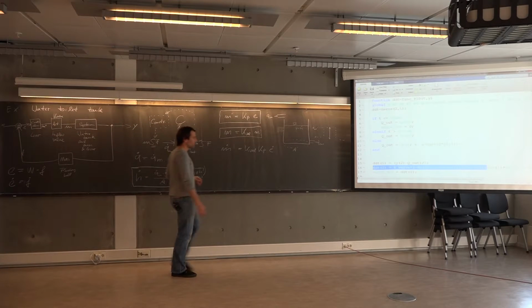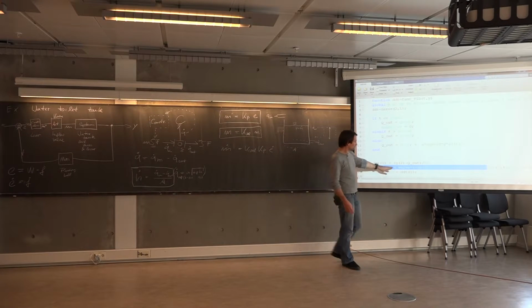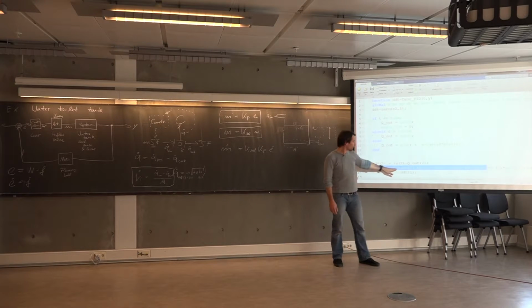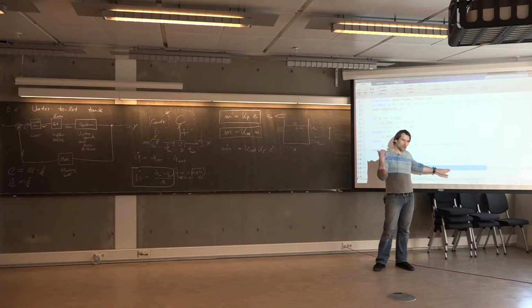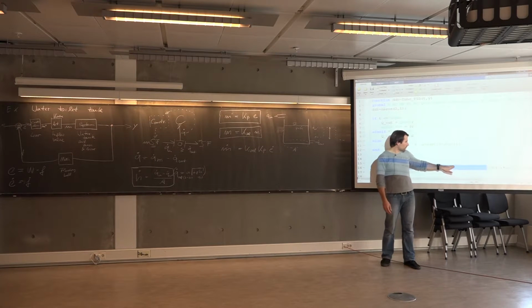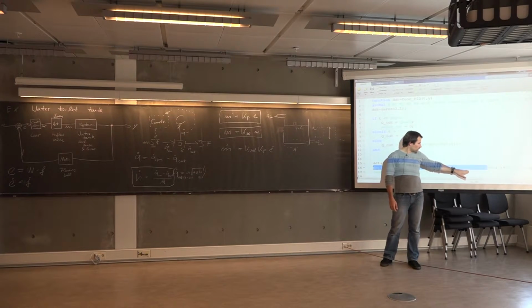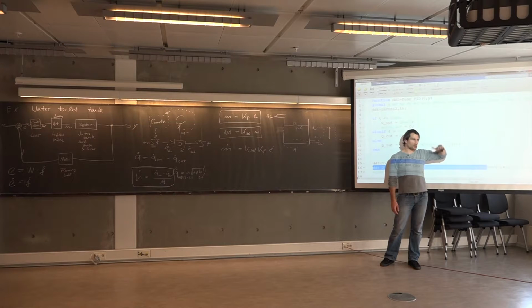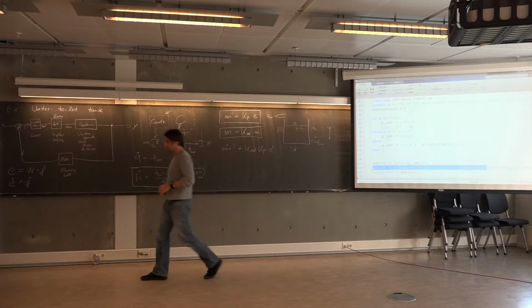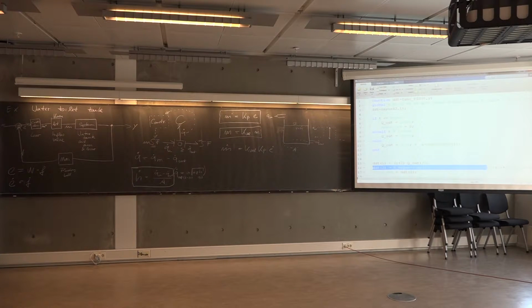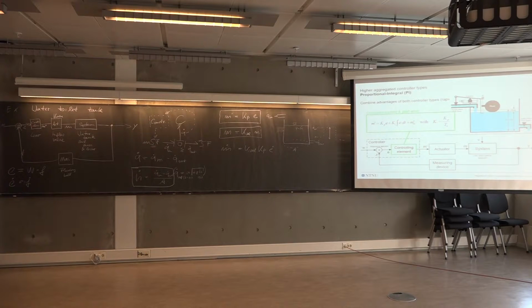We have this P proportional control term, the first one. And then we have the second part, the integral, which by taking the derivative we have sort of transferred to the error itself. So we have this integral constant here, Ki, and the error, which is the difference between the reference level, the height of the water tank at 0, and the current level. That's pretty much the only change in the controller.